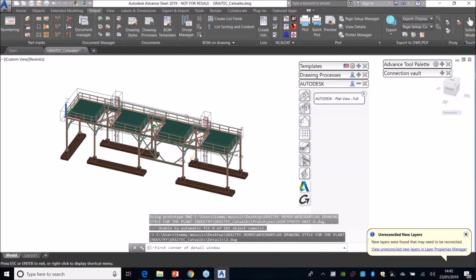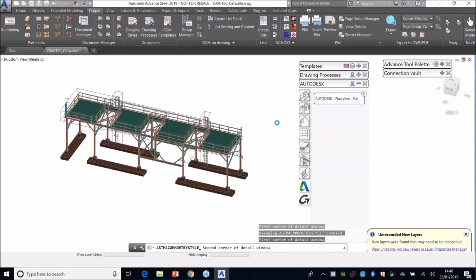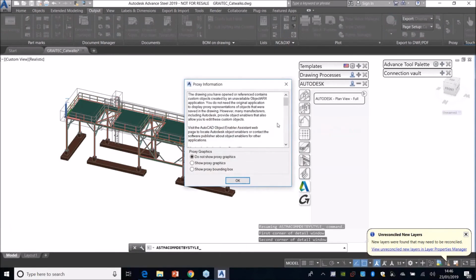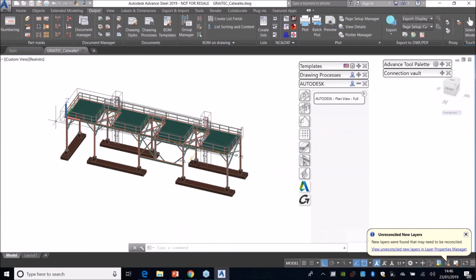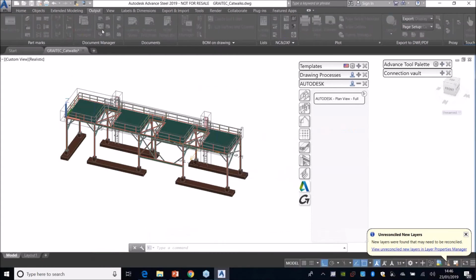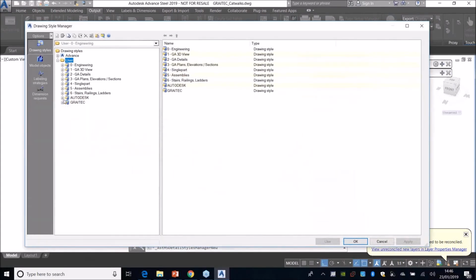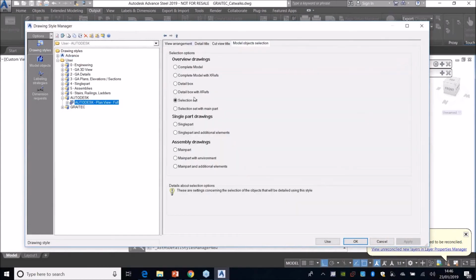Now you may be wondering why it asked me to select the objects as opposed to just selecting the view based off of 2-point selection. Well, that's a default setting that you can modify. In some companies, in order to avoid showing too many objects, if there's a lot of clutter with supports underneath and so on, some companies like the approach of selecting the objects required as opposed to just windowing based off a 2-point selection. Those settings can be modified here.